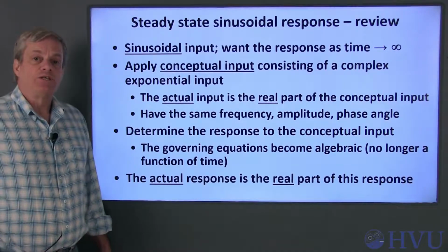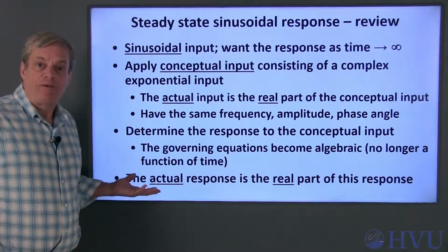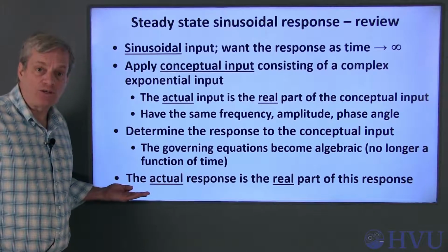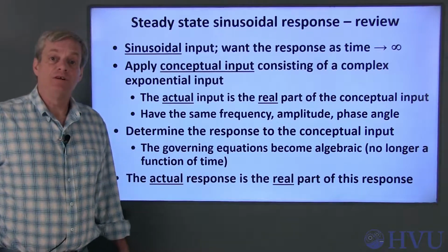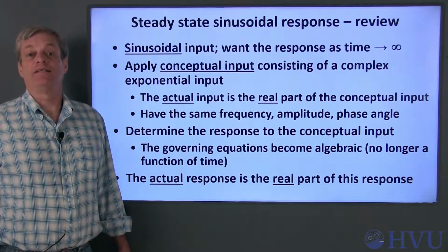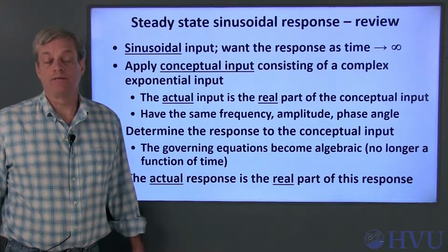When we solve the resulting algebraic equations, we're determining the form of the complex exponential response. The actual response will be the real part of this response. So the magnitude and phase of the calculated response will be the same as the magnitude and phase of the actual sinusoidal responses.